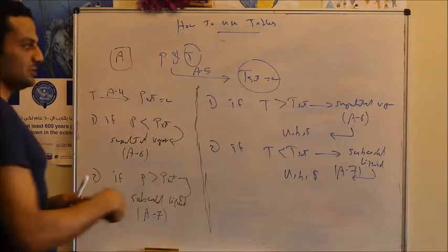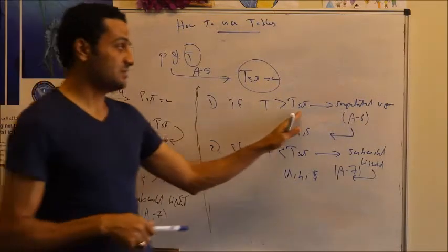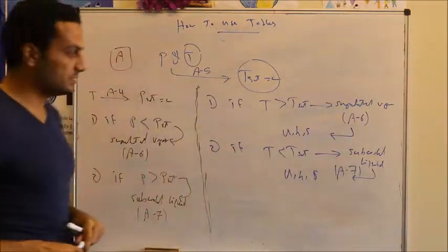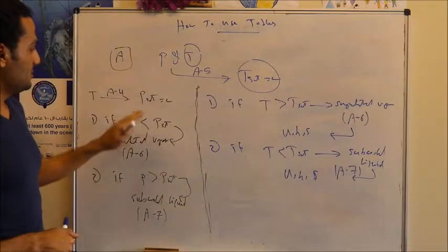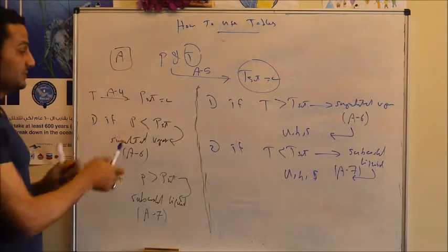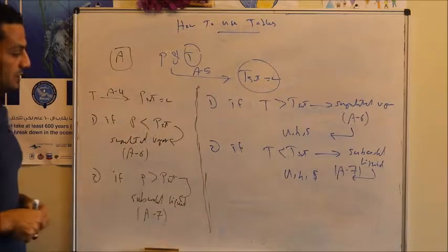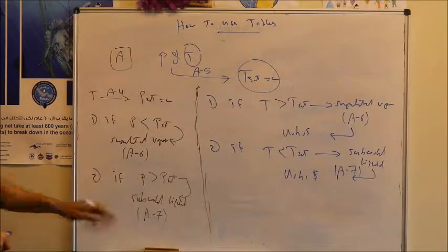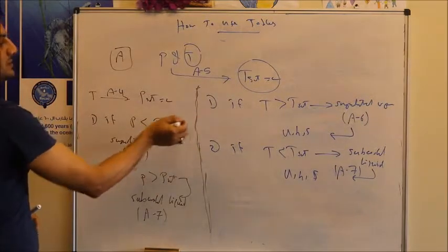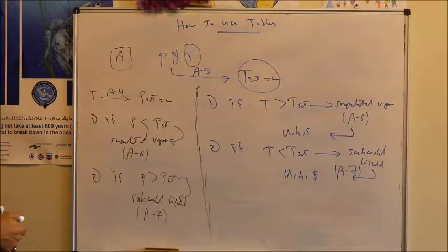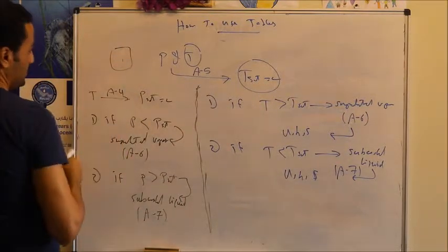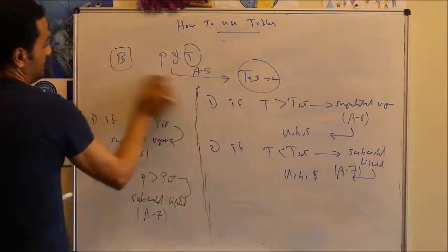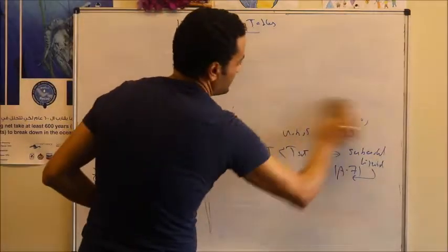But what you keep in mind is the temperature. If temperature is greater than T saturation, the state is superheated. If temperature is less than T saturation, the state is subcooled. Okay? So usually pressure is the reverse. If pressure is less than P saturation, the state is superheated. If it is greater, the state is subcooled, and in this case I have to use table A7. You can follow either these steps or those steps if pressure and temperature are given, and this should be state B. Okay, right, let's look at state C, another option also.